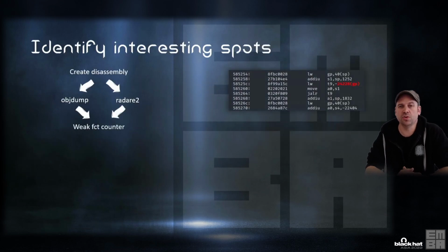For this, you can use different techniques. The easiest one, for example, is to use readelf. Readelf on every binary of the firmware, and you know which binary is using such legacy functions. But then you do not know how many times such functions are used per binary.